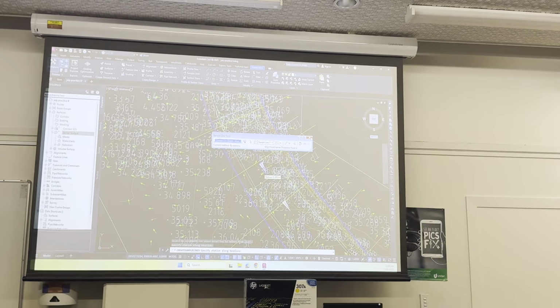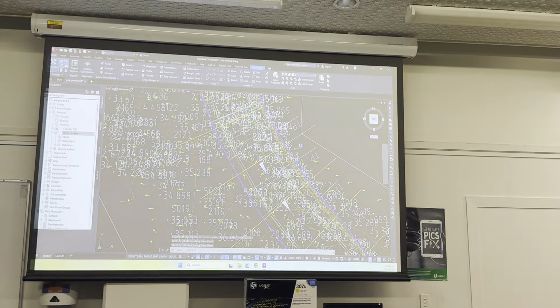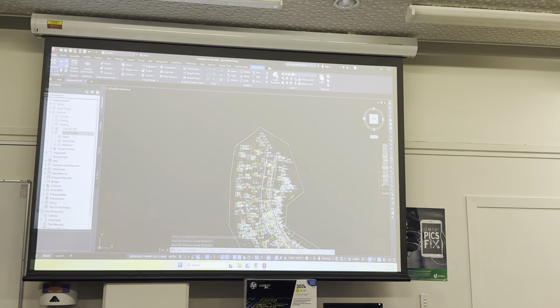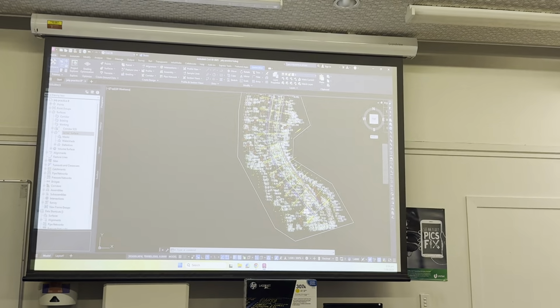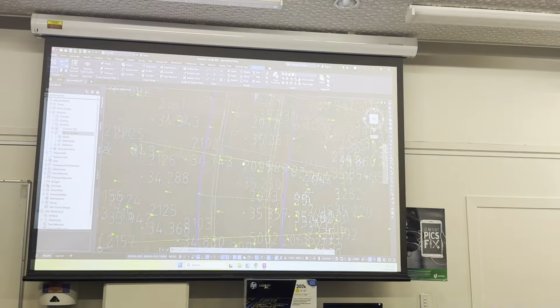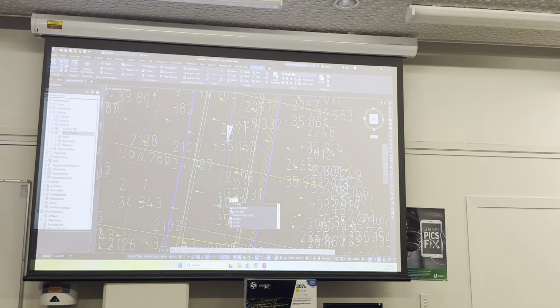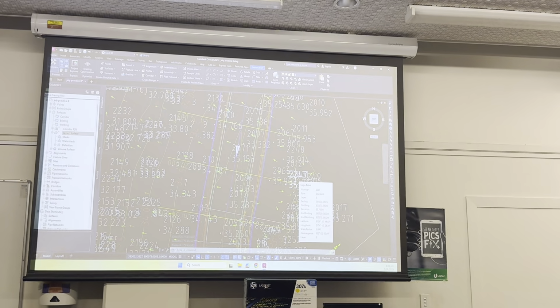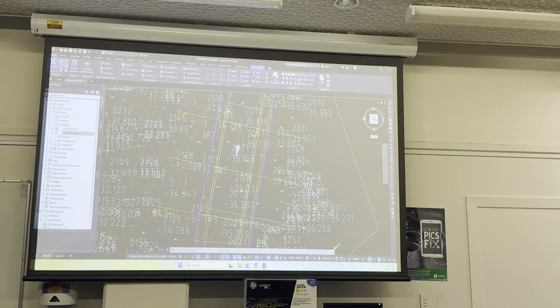If we exit the sample line tools, we can see that our sample line stations have been created. They are every 10 meters, like what we typed in the properties box. We can double check that. 10 meters. Cool? Thumbs up? Alright, we'll move on. Click the Escape button.